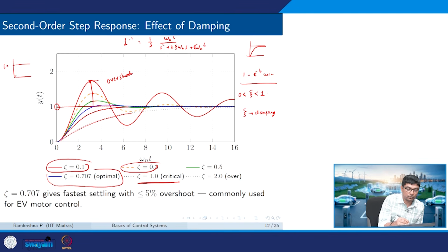Okay. So, will I go like this, because everybody wants to go fast, right, or will I go like this? If I want to go from 0 to 60, maybe I can go till 66 and come back and then slowly try to accelerate. I just put my pedal in such a way that I first overshoot 60 and then I come back and so on, right. Of course, I do that a little adaptively when I drive my own car. But in general, it is allowed to go above 60, come down to maybe 54 and slowly settle down, right, because I want a faster response.